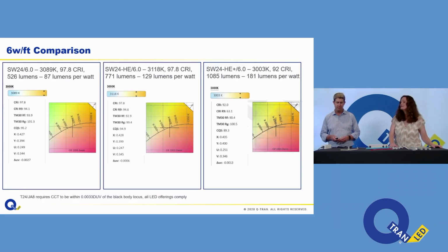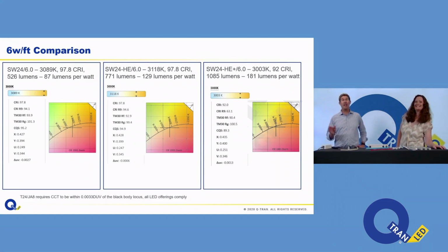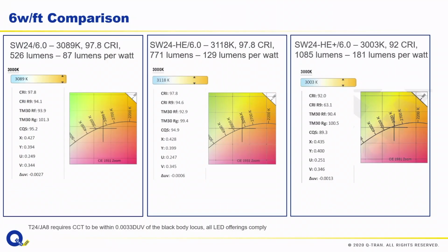Okay, next. How good are these LEDs? How good are they? Let's look at this HE slide actually big so we can read it too. The SW and HE are one step, one bin. And so we're over 95 CRI. Our R9 is also over 95. And we're really right there on the black body. The HE Plus, we're sacrificing a little bit. So we're at 3-step.